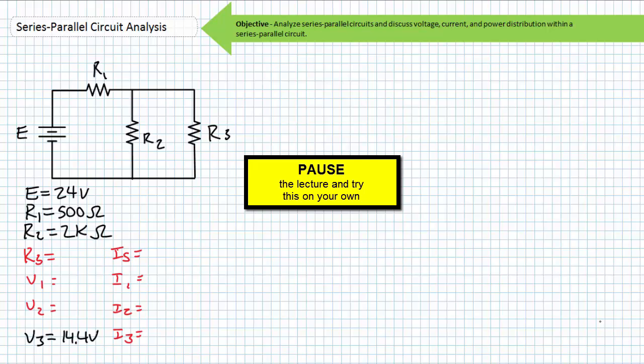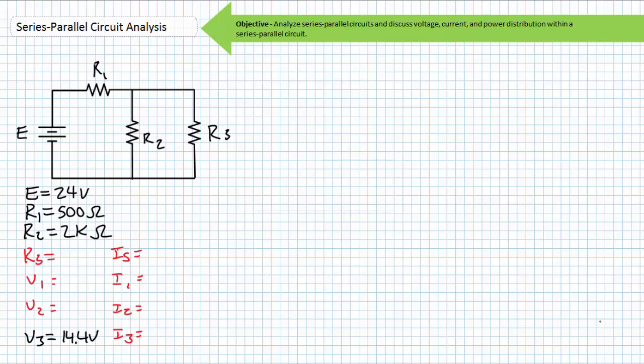Visualize this circuit at the nodal level and from the perspective of flowing current. Current in a single path is the same. Voltage across paths in parallel is the same. For every rise there is a drop, and what goes in must come out. I'll start by assigning some nodes, A, B, and C. Source current leaves the positive terminal of our source and must pass through R1. It can be said that IS equals I1.